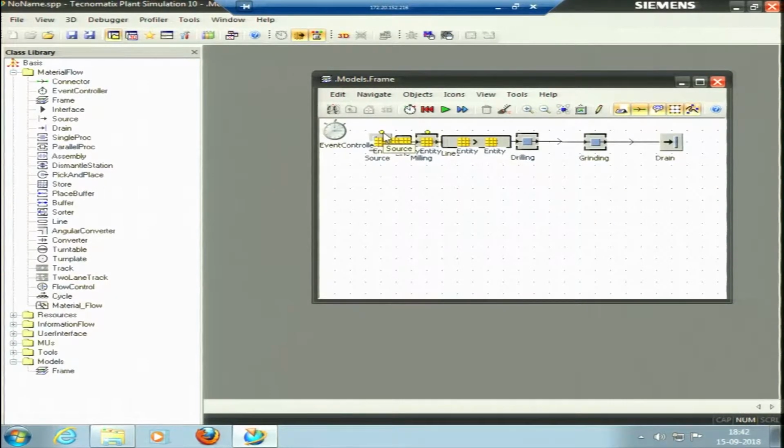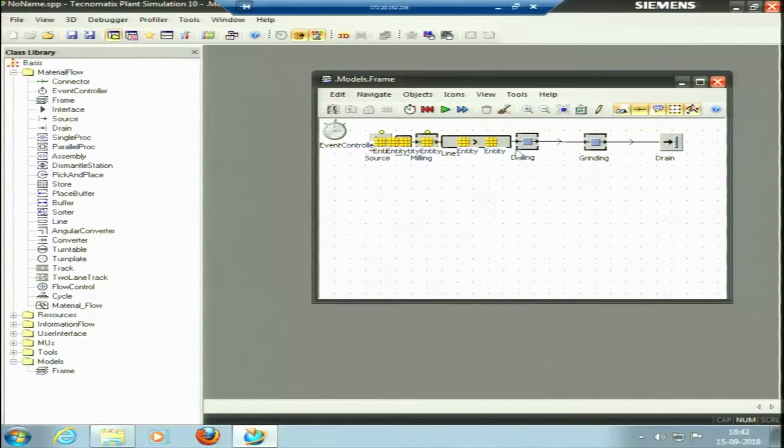Successive conveyor is completely filled, and the predecessor, that is our source here, or the entry line 1, is blocked because the successor is waiting. The successor is completely filled, and it cannot transfer its material from its own point to the forward process. So if this capacity is 2 now. Okay. Now why is it not connected to here? It is stopped here, it shouldn't stop.